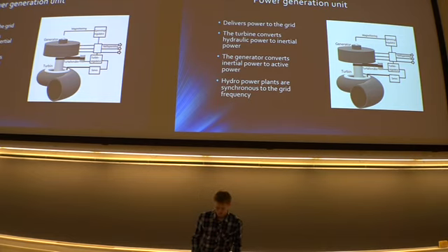So I made a small figure, and I'm sorry about the language for your English speakers, but the governor is this block right here, which senses the RPMs of this power unit and calculates the openings of the guide vanes of the turbine based on the PID algorithm.